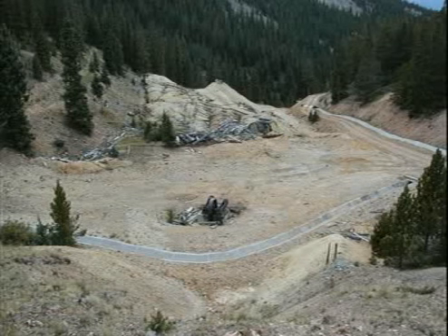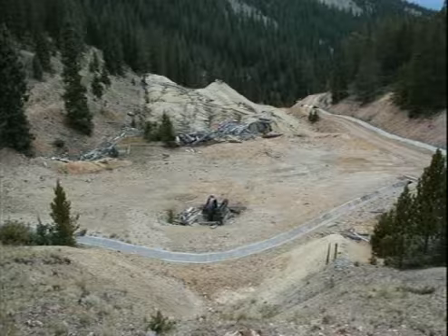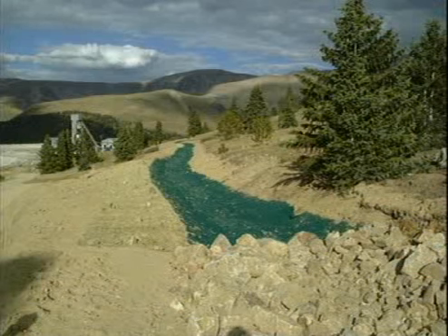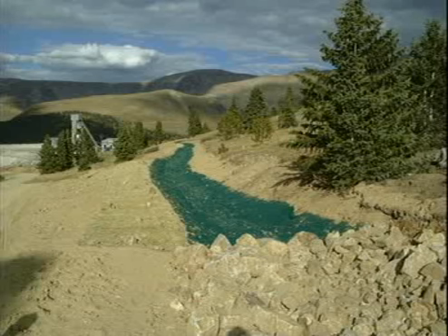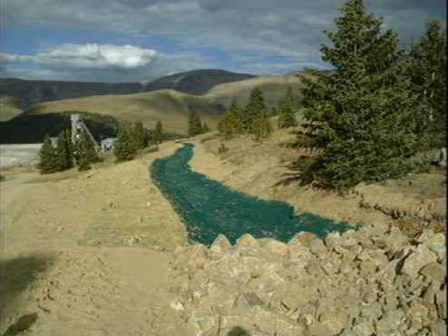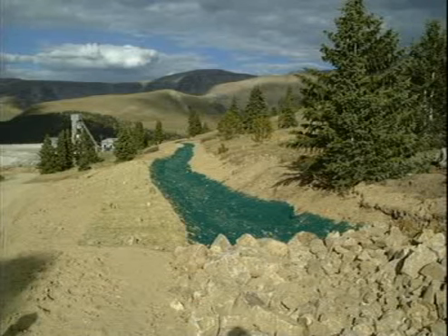Here's another slide. This is an example of two types of ditch. In this next slide, we're looking down a ditch. We have one type of ditch in the foreground and another type in the background. The near ditch is lined with riprap, fairly coarse here, kind of boulder size, and the far ditch, the green part, is lined with a jute mat. In a year or so, that jute mat may cover over with grass and soil, and it'll look more like the native landscape.